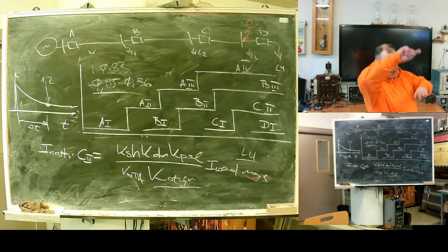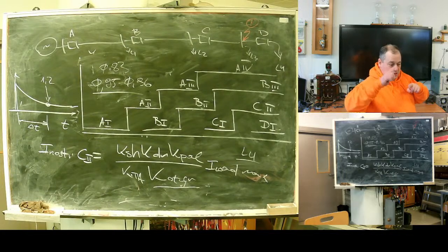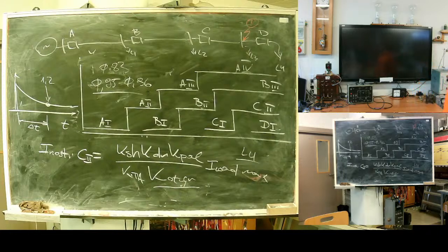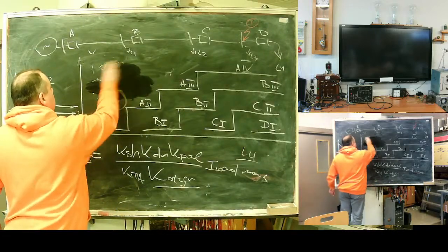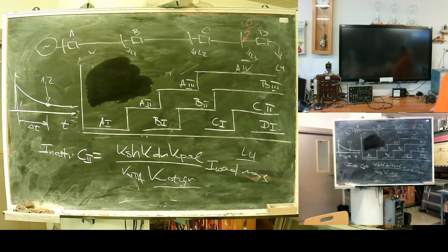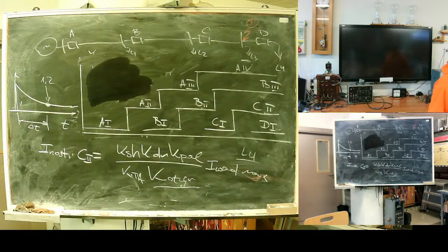If you don't have this hysteresis loop, the relay will trip, return, trip, return, trip, return. Why do we need it? So hysteresis of 4-5% is a good measure against this trip, return, against shake trip. This factor plays no role for instant zones, but for delayed zones it's important.